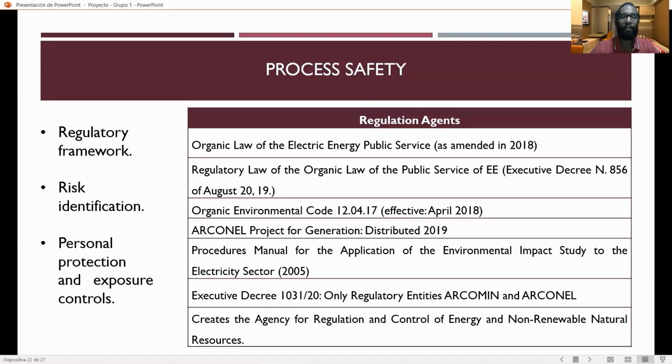To avoid some of the possible dangers present in a cogeneration power plant, periodically it is necessary to carry out an evaluation of the pressure, temperature, and flow indicators, safety valves, boilers, tanks, and corrosion control to protect industrial safety. Personnel should wear heat-resistant gloves and protective goggles to prevent any substance from entering the eyes. Ear protectors should be worn to protect the hearing. Helmets, boots, and overalls must be worn. For emergency control, full protective clothing should be worn, including safety goggles, gloves, and vapor respirator.